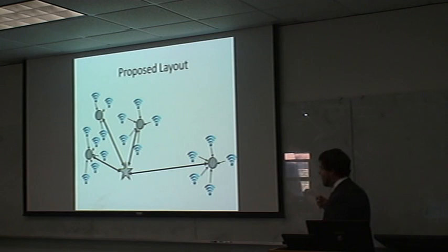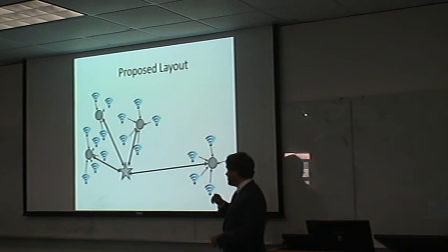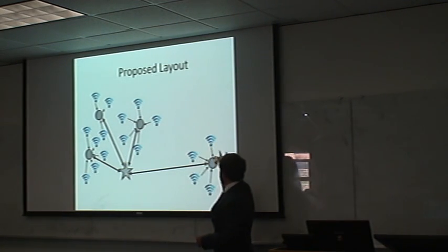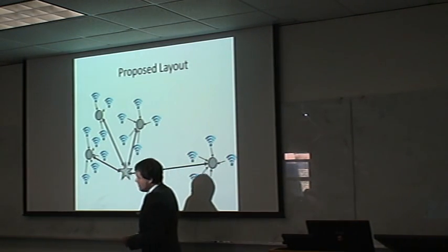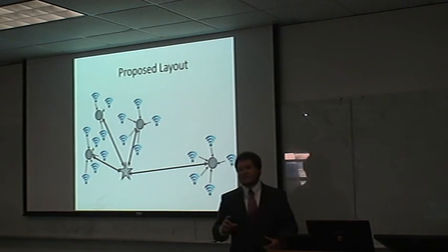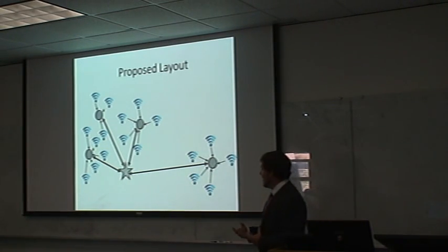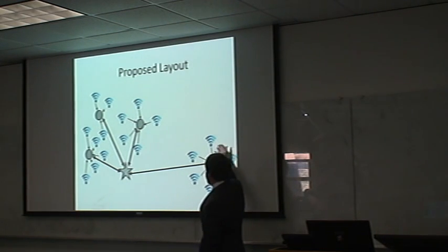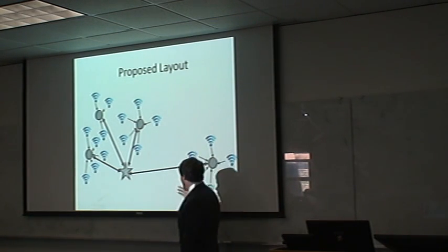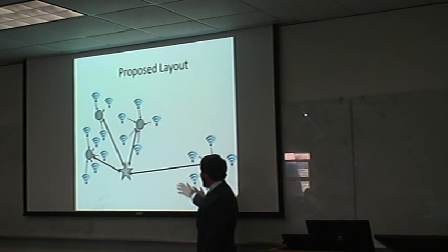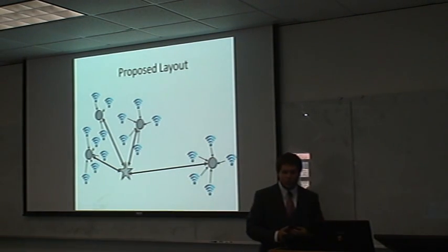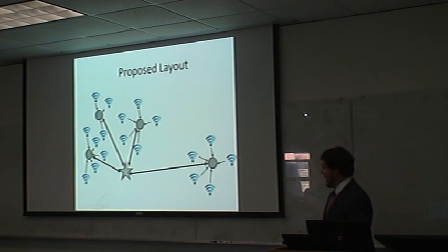So if we step back from that and say this is the entire greenhouse, each one of these blue wireless signals here would be one of those sensors. These gray dots here, or the gray circles, would be what we're going to use as repeaters. And again, that's that connection between the wireless and the wired. So this cluster of sensors is too far away from the main base station to wirelessly transmit back. So we don't have enough power to do that. Again, so we're going to have that wired system that goes back, and that allows us to reach further than we can do with our wireless and manage the size of that battery. So that would be the inside of a single greenhouse.